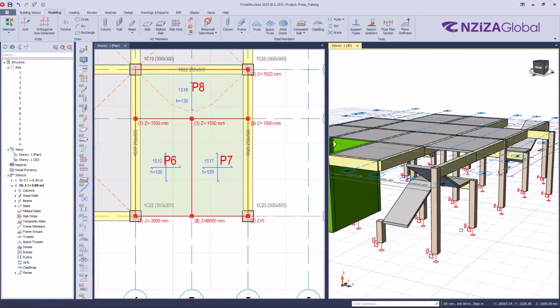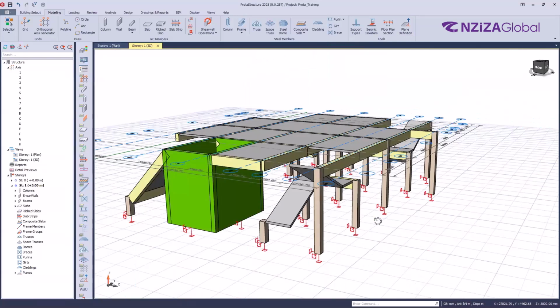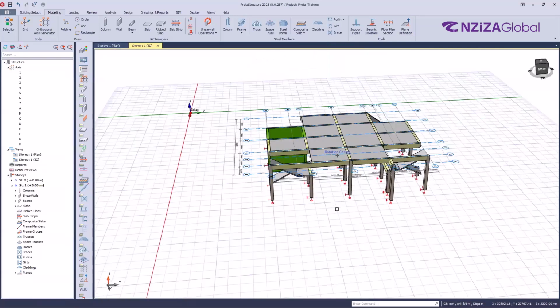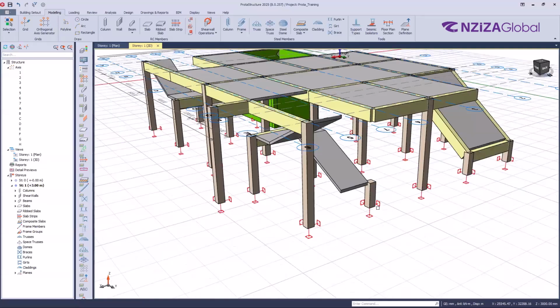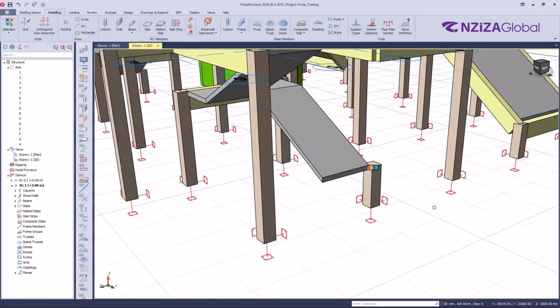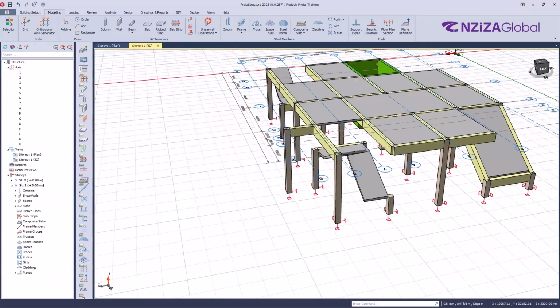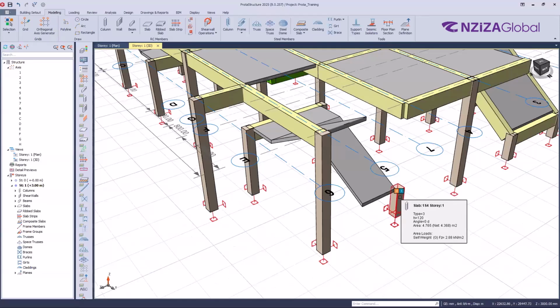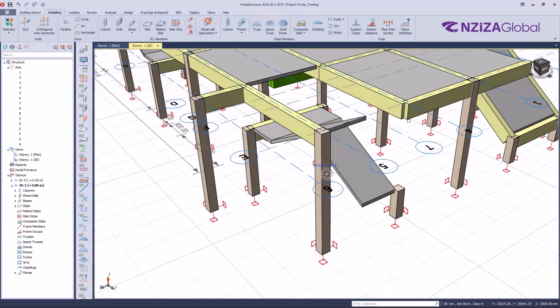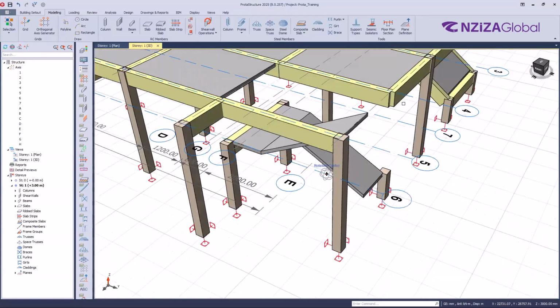Good. So the last point I want to mention before we go for the work time. If you check well, if you apply plane definitions, even the columns, even the beams follow the plane, but sometimes you may not want that to happen. For instance, I have applied a plane to this slab, then the column has been shortened. Now you see I have an issue here. The column must go all the way up here.